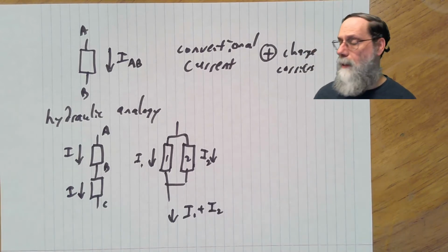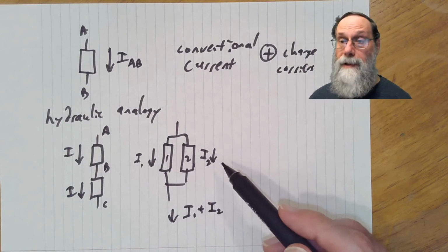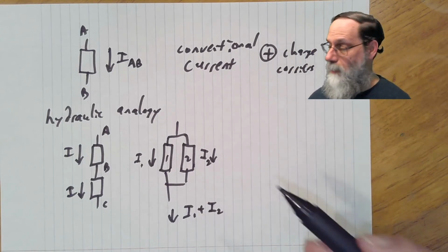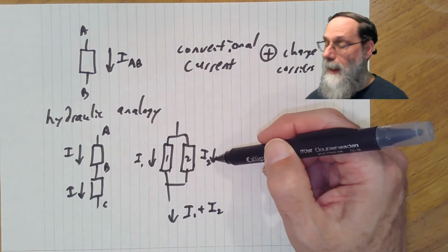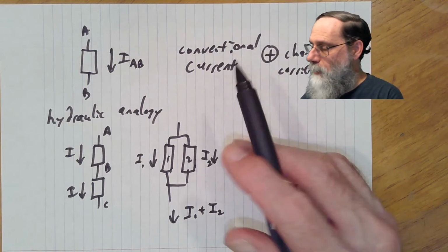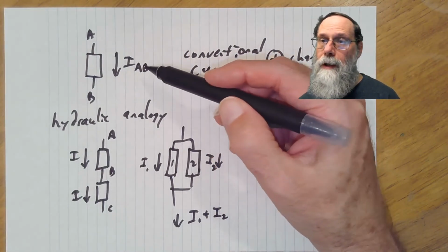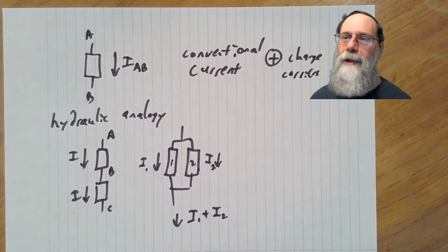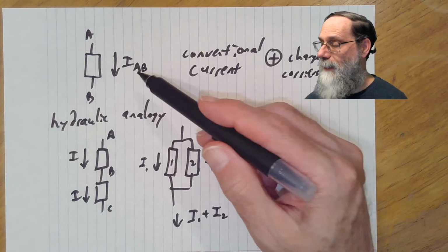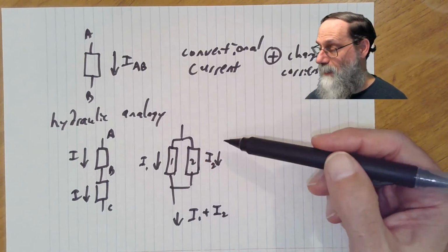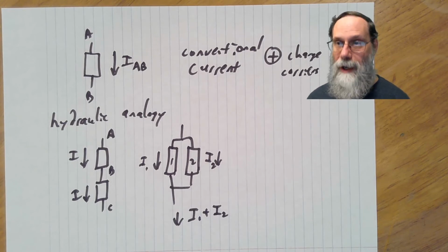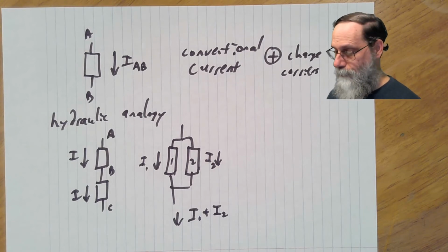And when I draw currents, I often like to draw them as an arrow to indicate which way positive is. So that if I put a positive value on I2, that means the current is flowing in that direction. It's also possible to do it with the subscript notation, but quite often we don't name all of our nodes, and so if this node isn't named, there's nothing to give subscript for. But I can still draw an arrow next to a component to say which way is the positive direction for current flow through this component.